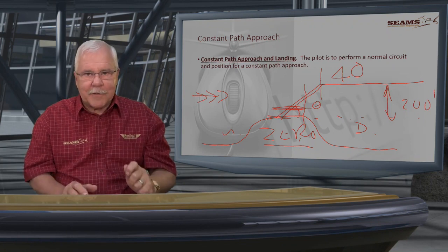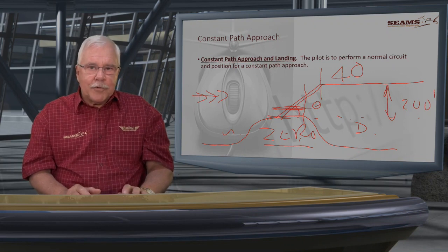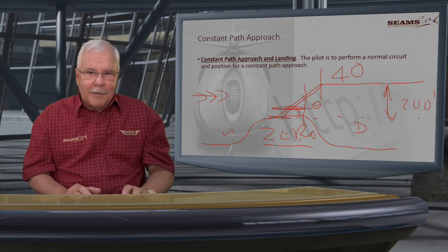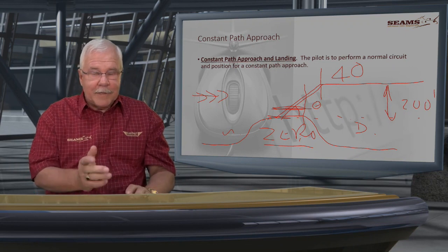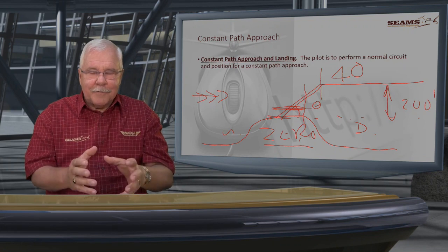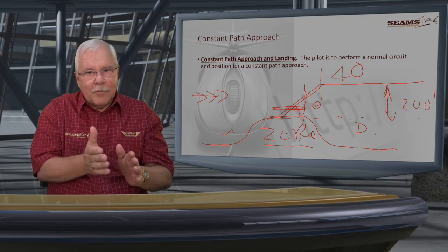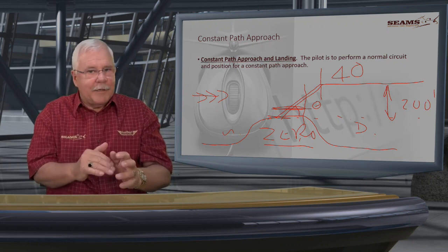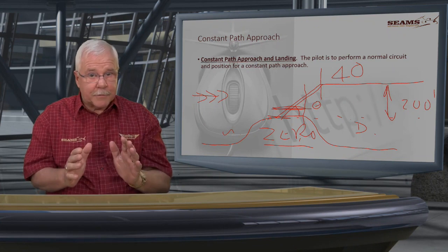Believe me, the collective is only there for the climb or rate of descent, and if you should change anything, then you must touch up here to maintain the rate of descent. What is the rate of descent? 300 to 350 feet. If it's up to 500, you must get it back. If you can't, and it goes beyond 800, you've got to break off. Okay? Those are the rules.